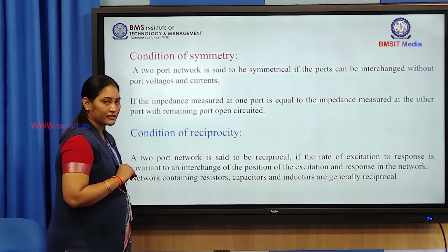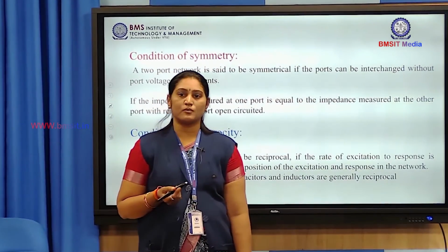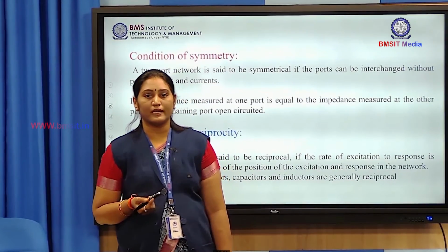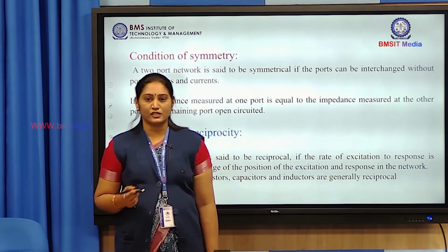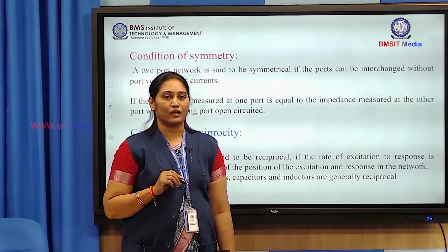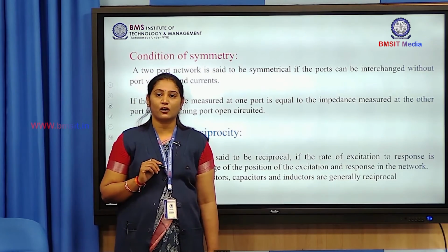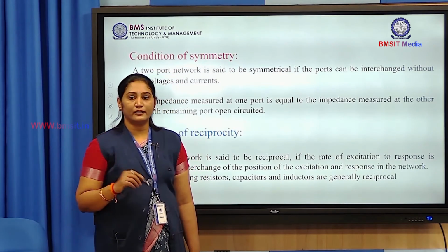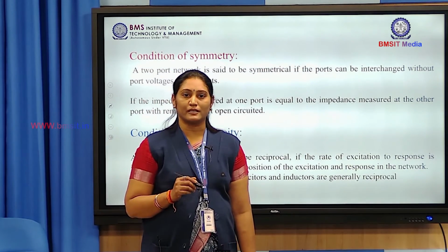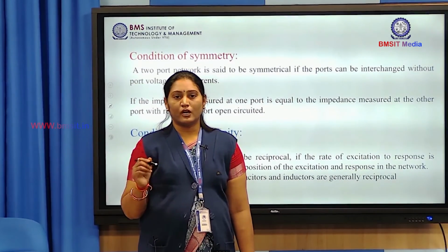Okay. Now the condition for reciprocity: when can a network be said to be reciprocal? A two port network is said to be reciprocal if the ratio of excitation to response is invariant to any interchange of the position of the excitation and the response in the network. What does that mean? If a network is reciprocal, even if I interchange the excitation, that means the sources, the parameters, Z parameters or H parameters or any other parameters, will not change in value.